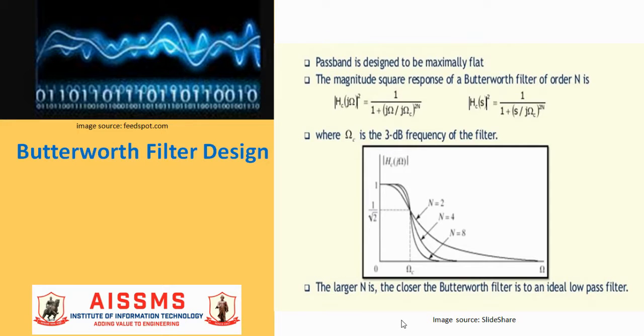Infinite impulse response filter design techniques are all based on converting an analog filter to a digital filter. The digital design starts with analog design and maps the analog filter from the S domain, that is the Laplace domain, to the Z domain, that is the digital domain. It is necessary to approximate the characteristics of an analog filter, as the practical characteristics of a filter are not identical to the ideal characteristics.